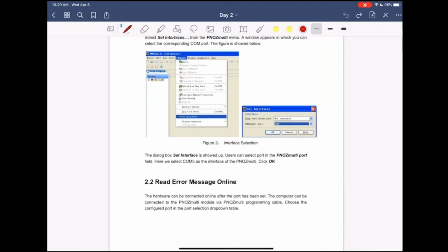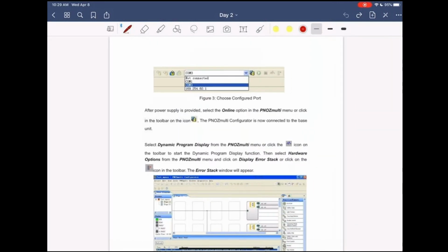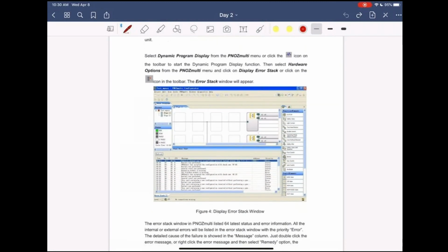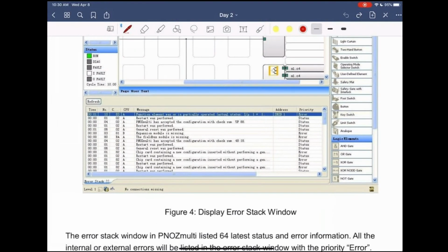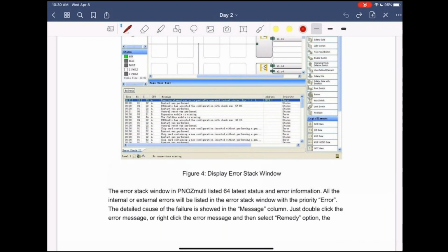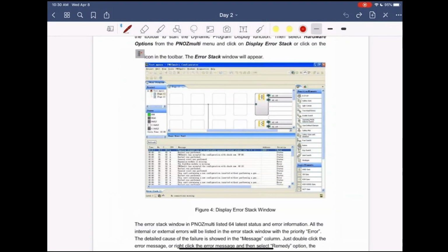But if you want to look up error codes, you can do that. We do have our service guys capability, and we always like to make sure that they have the proper tools to troubleshoot these PILZ units, because it will give you an error code. If you have a fault, it'll tell you what the error codes are, and it'll tell you where the problem is, which is a little bit easier than trying to figure it out by looking at the lights.